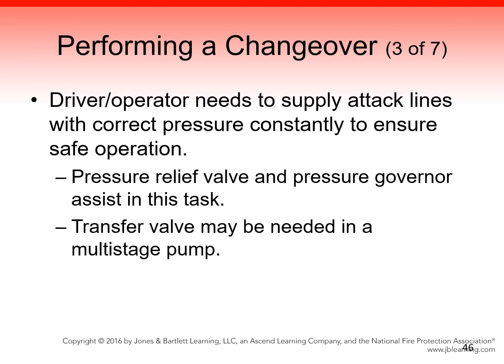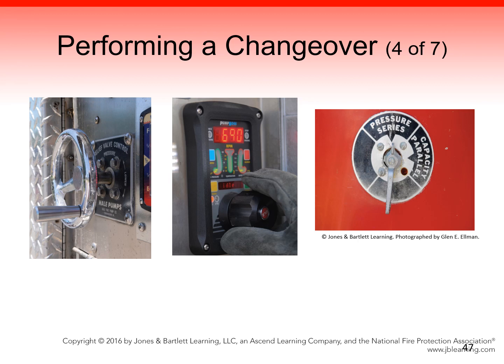As the driver-operator, you need to constantly supply the attack lines with the correct pressure to ensure a safe operation. Two devices that will assist you in this task are the pressure relief valve and the pressure governor. In a multi-stage pump, you may also need to use the transfer valve. Figure 11-17 shows a pressure relief valve. Figure 11-18 shows a pressure governor, and Figure 11-19 shows a transfer valve.